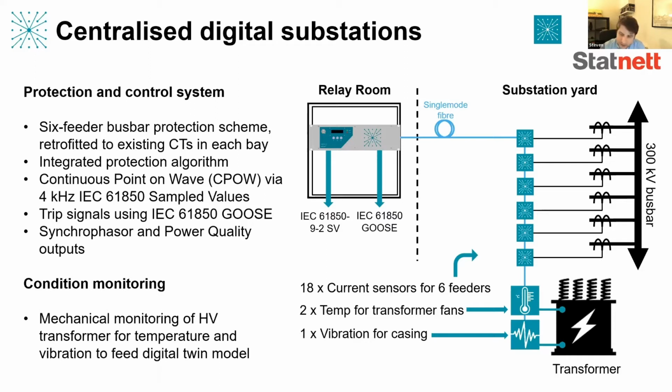So effectively with this architecture, we've eliminated the need for a merging unit and all of the redundant telecoms requirements that brings along, and the time synchronization issues that are frequently encountered when trying to configure and deploy these devices. So we've immediately removed a lot of the complexity and removed some powered devices that would need to be installed out in the substation yard. So we're already simplifying the approach.